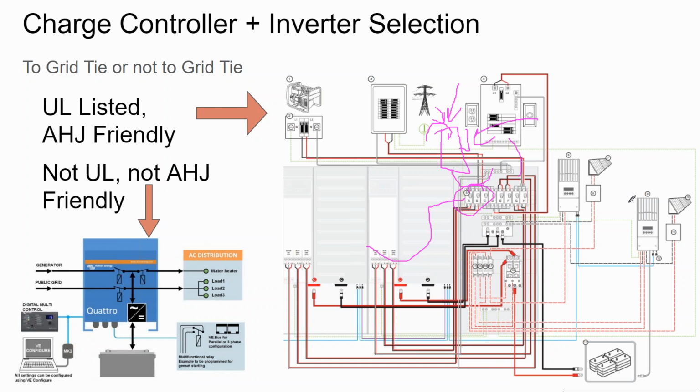And yet it's a readily accessible requirement, which means that anyone can walk up to that disconnect switch, turn it off, open it up, and stick their hand inside and electrocute themselves, because they don't understand that the top of the disconnect switch, just like the top of a utility meter base, could still be hot when the system is de-energized.